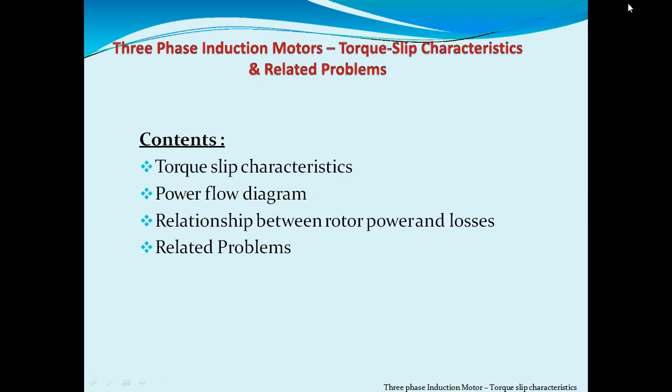Then we saw the rotating magnetic field. When we are giving the three-phase supply, we use the phase sequence RYB, the standard phase sequence to rotate the induction motor in the clockwise direction. Here, instead of single phase, we are using three-phase supply, which we can give in the star or the delta connection, and we are using the sequence RYB.